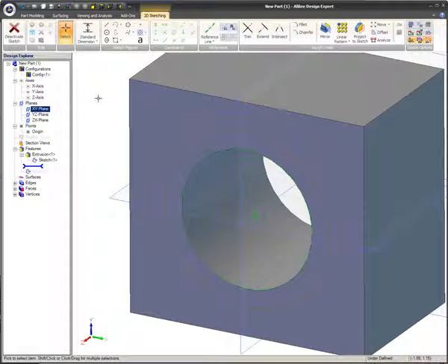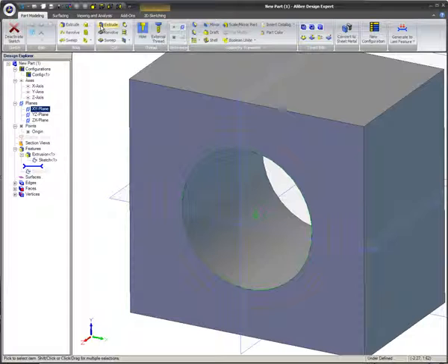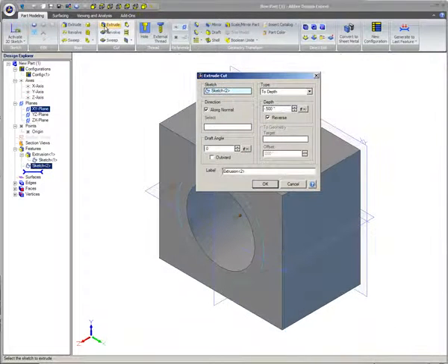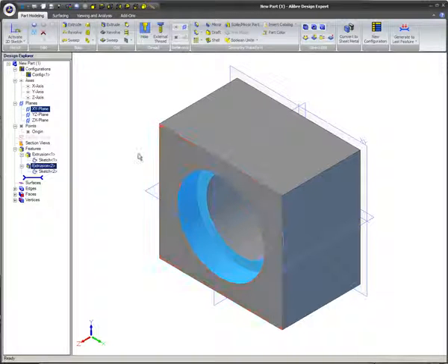You have also learned that some sketch constraints are used to apply relationships between figures, for example, perpendicular, tangent, parallel, and equal size, while other constraints are applied to individual figures, including those that control a figure's orientation, for example, horizontal or vertical, and dimension.